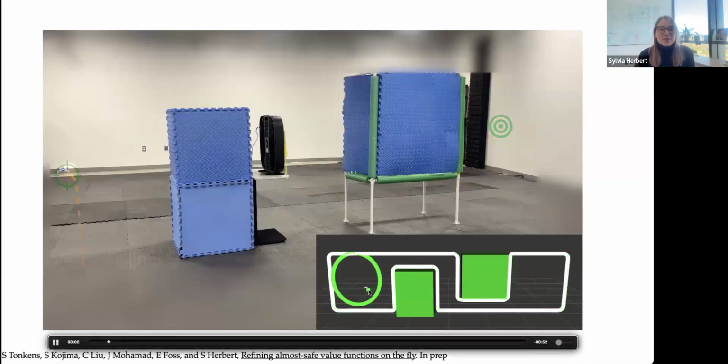And so we're going to select waypoints that are as far to the goal as possible, but still inside the current safe set. So you see the waypoints being selected as the safe set keeps growing and growing. And then here, when it detects this wind, it has to update its safe set based on the sensed wind and the new disturbance bound.